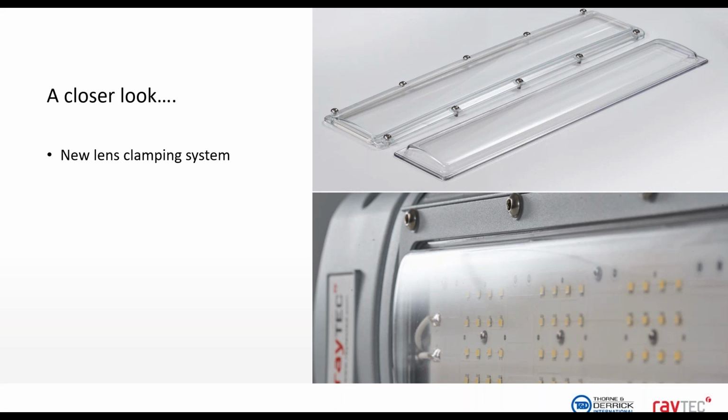And it's around those screw holes, which you can see on the existing lens, where damage or cracks were most prone on the old version of the luminaire. We still think that old luminaire, the generation 1, was a very good product, very robust and resilient. But if there were areas which were prone to issues, it was around those screws. So taking those screw holes out of the design removes those stress points, and allows that improved impact rating and that improved chemical resistance that we talked about in the previous slide.